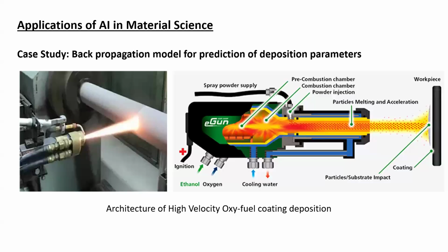That XYZ material, in powder form, is fed to this combustion chamber. And when that temperature increases to 3000 or 4000 degrees Celsius, that powder will get melted. Once it is melted, it is then deposited on that particular biomedical implant that we have.